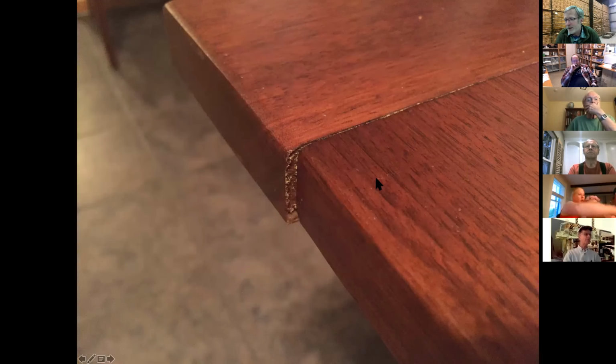Well, we know now that the tangential plane of reference shrinks twice as much as radial, but also that wood only shrinks about 1% in length, right? From green to dry. So the length of this piece is hardly moving at all, but in the wintertime, the width of this table is moving significantly. But notice also, it's shrinking a little bit in thickness, and you can see that in the bead, right? So it's shrinking in width and thickness.